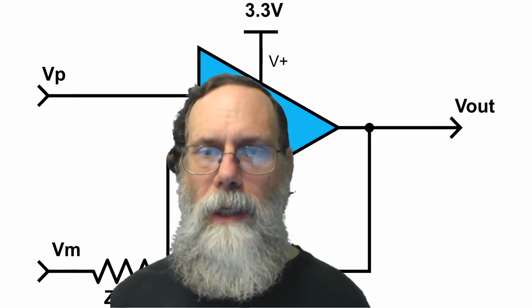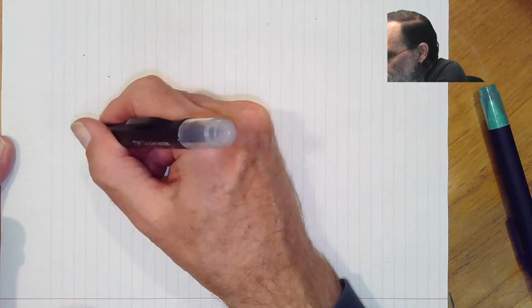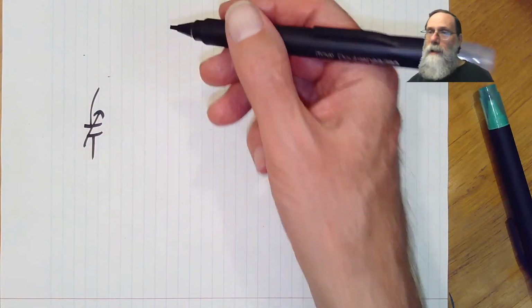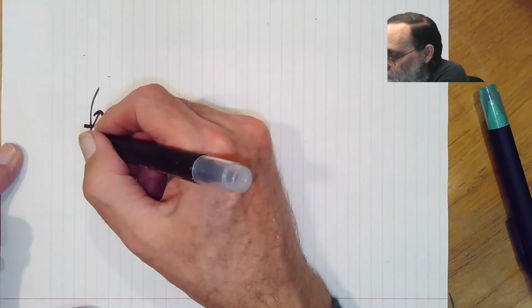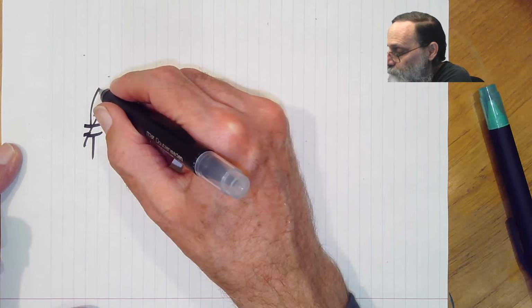Let's take a look again at how the junction field effect transistor is used in the microphone. We have a variable capacitor here, that is the diaphragm and the electret, and it varies with the air pressure on the microphone.